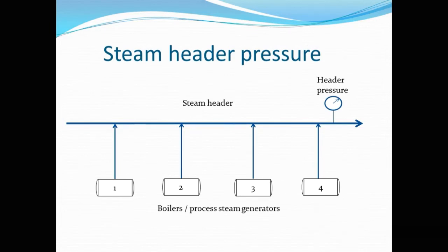They are not worried about where the header pressure moves. Since the mass input to the header comes down while the output remains the same, the number of molecules in the steam header will come down, resulting in a drop in steam header pressure. Since the system pressure is coming down, the boiling point will reduce.